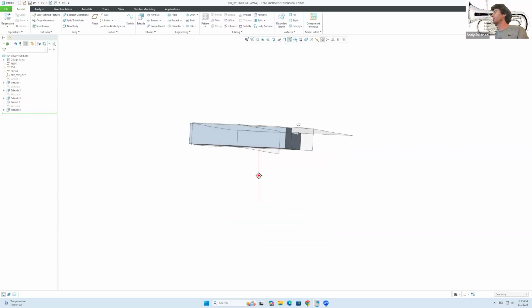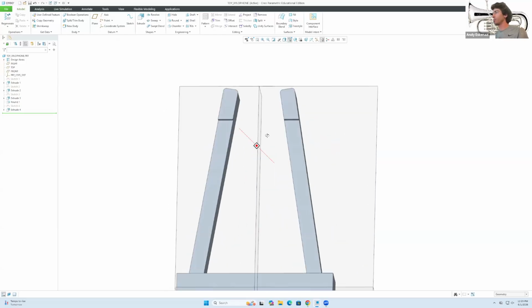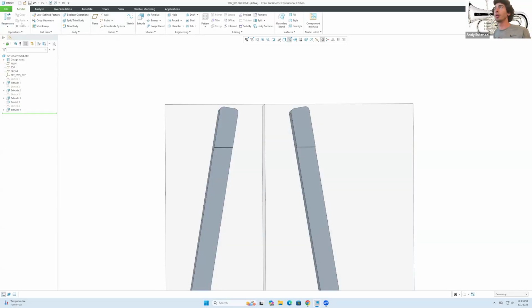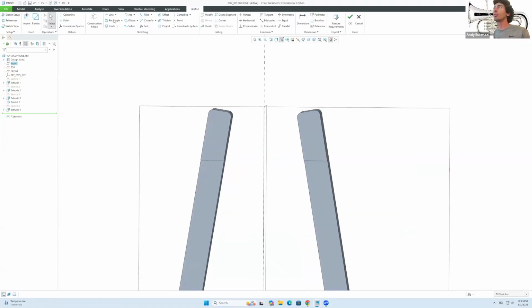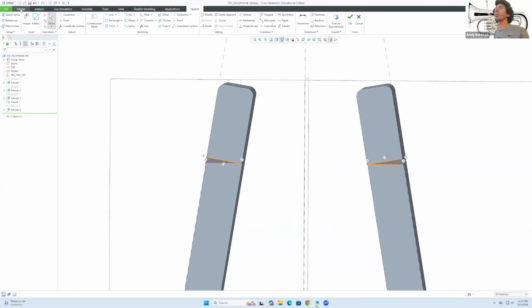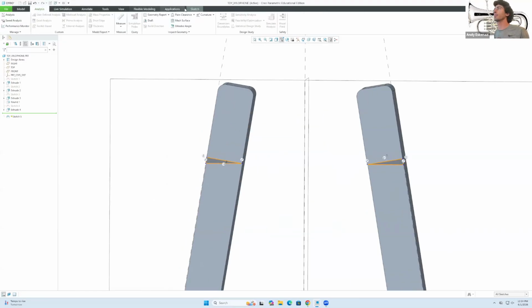And now in the theme of this piece, we're going to do the exact same modification that we did earlier, where I'm going to go here to sketch that face. Good. And now we're going to try to create 2 little triangles that are going to go just like that. And now let's do it here. And now we go here to perpendicular, and I click on those 2. Perpendicular, excellent. And now we go here to sketch.